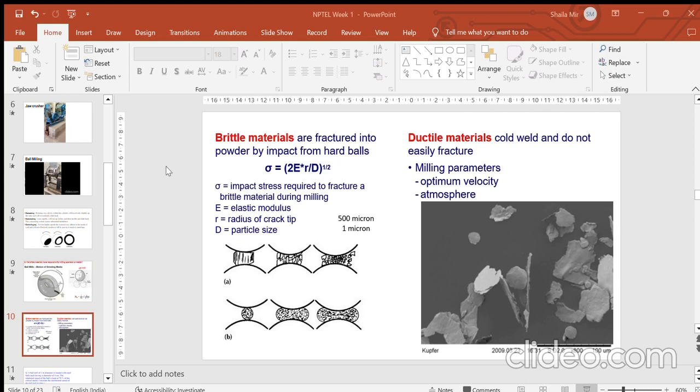So we have a ball mill of diameter 2 meters, with steel balls of diameter 4 centimeter loaded in it, and the rotational speed of the mill is kept at 70% of the critical speed. You have to calculate the operational speed of the ball mill. First, you have to calculate the critical speed. After that, you have to calculate the operational speed of the ball mill in rotations per minute. So you can take 5 minutes to solve, then I'll also solve it.